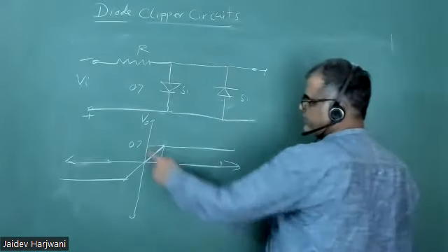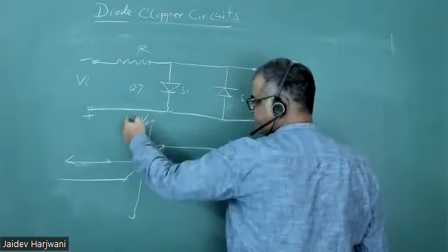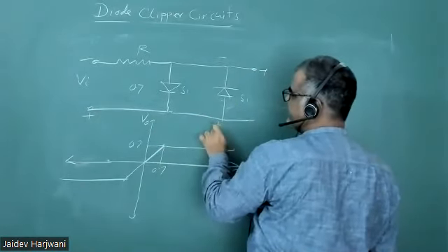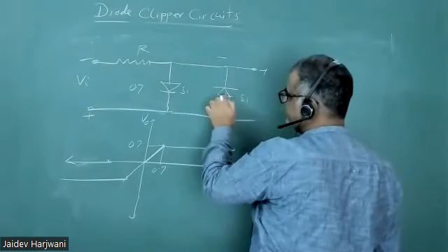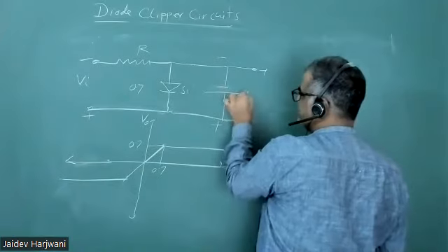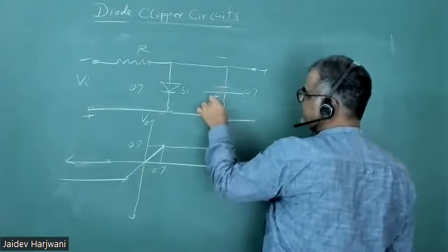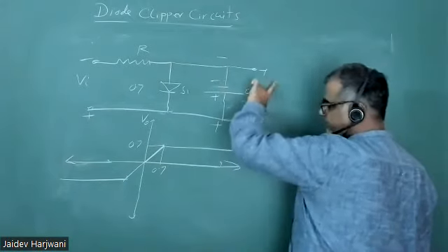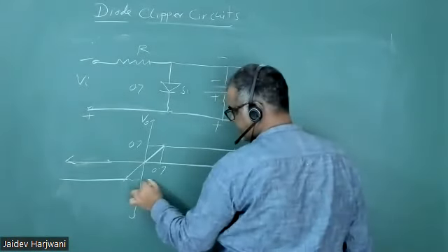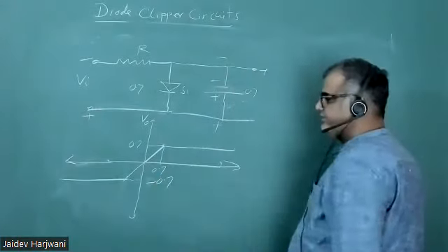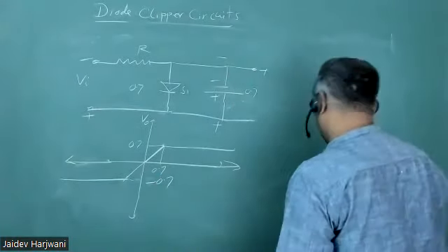Now what I'm changing here: when this voltage reaches greater than 0.7, this becomes a diode, and now this is 0.7. This is minus 0.7, I'm measuring like this. So this will always be minus 0.7. V output will be negative. This is the graph.